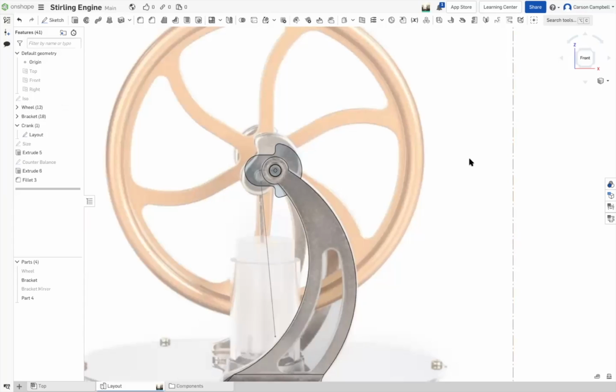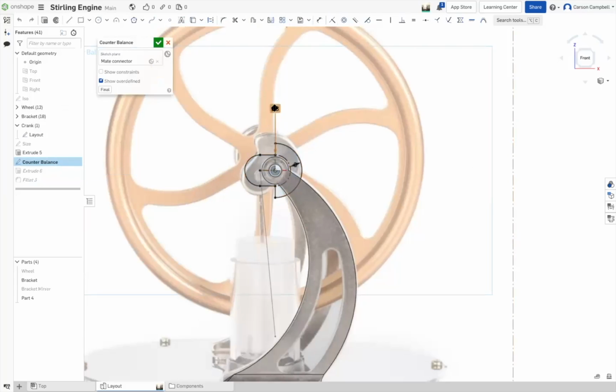The other thing is, let's double click counterbalance and let's go to the 7mm diameter instead of 8, because I want to see more differential. Now, if you start doing FEA, you're going to need that. Okay, and if we do that, then go ahead and leave that at 7.